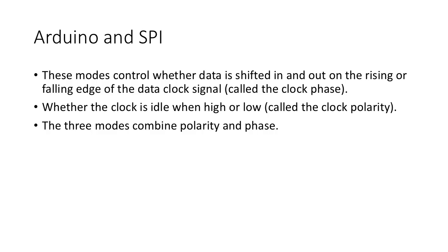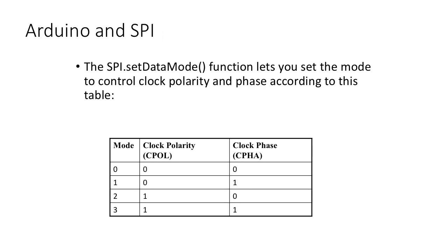The control mode transfers are based on either rising or falling clocks. And you can choose whether or not you want a rising clock or a falling clock for the transfer of data. That's called the clock phase. And so you can choose the various modes, and you can see they're numbered here in binary as well as in decimal on the left. And this enables you to choose the mode in which you do your transfer.